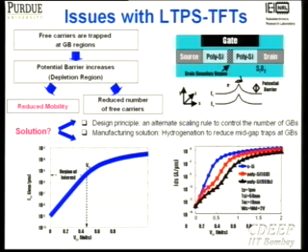Using those two solutions, we plotted the standard silicon devices. We compared a 200 nanometer silicon device. In this particular case, a silicon device is actually an SOI. I'm not really sure if I considered SOI in this case, but anyway, I looked at crystalline silicon versus these kind of devices, which are very similar to a thin body SOI. Of course, in a standard thin body SOI, I would like to make my body thickness even smaller and my oxide thickness smaller too.